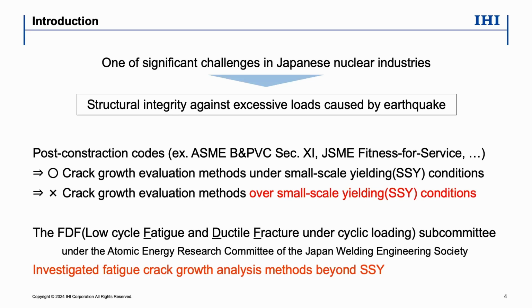The post-construction codes, ASME Section XI or JSME rules on fitness for service, clearly stipulate the crack growth evaluation method under small-scale yielding conditions. But they do not cover conditions beyond small-scale yielding.